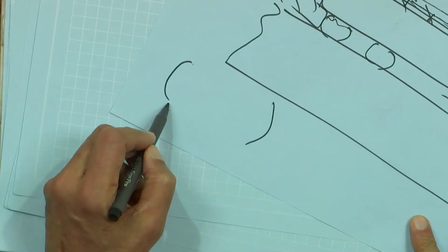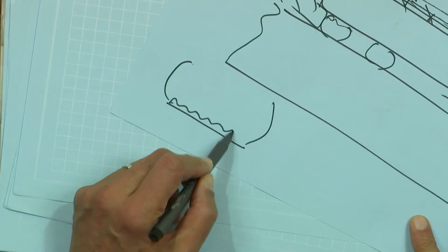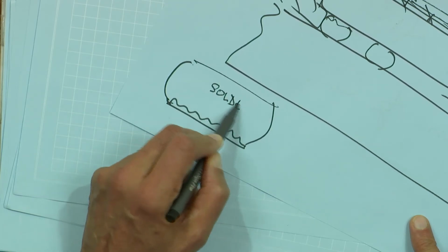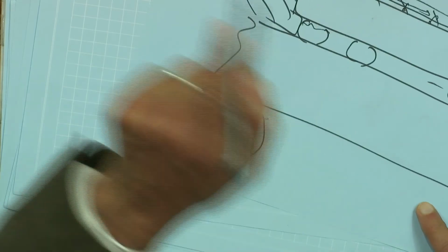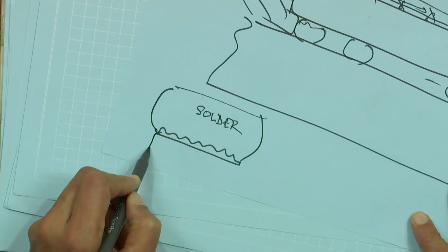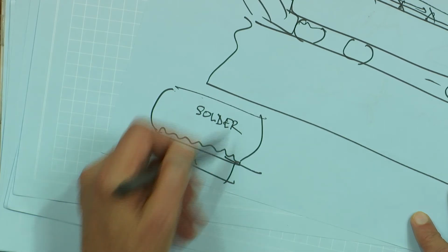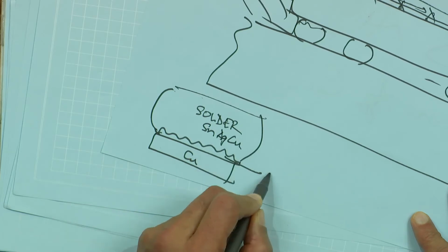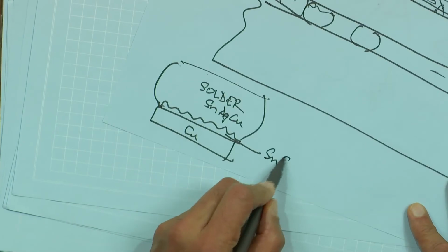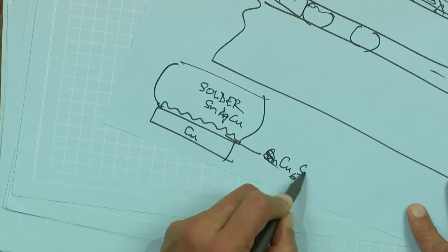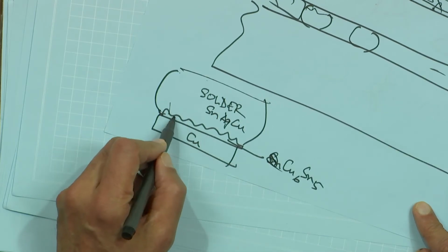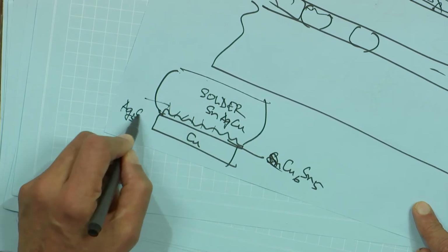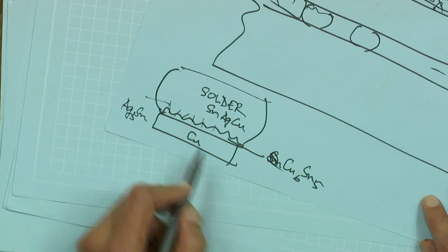So if you think about the intermetallic layer, it's a very wavy, scalloped kind of a material that forms. This is solder. Is that big enough? Can you read it at the back? Yeah, okay. This is copper, right? And let's say for this combination, if this is a SAC solder, then you form tin copper, so actually it's Cu6Sn5 intermetallics, and you form some silver also that forms off of it, Ag3Sn. So you form some complex intermetallics at that surface.